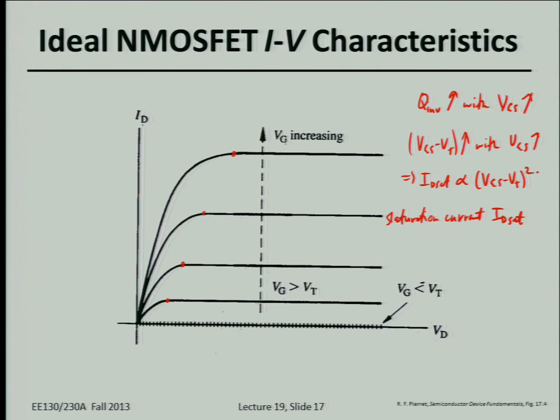Okay, so qualitatively, you should know this is the reason why the maximum current that your transistor can flow depends quadratically or superlinearly on the gate voltage, because not only do you have more inversion charge, but you can get up to a higher drift velocity because you can have more voltage applied across the channel inversion layer. So you basically have to draw a separate current versus drain to source voltage curve for each value of gate voltage greater than the threshold voltage. These are just curves for transistors in the on state.